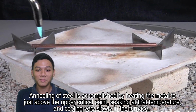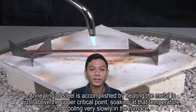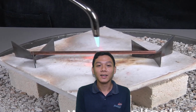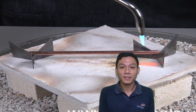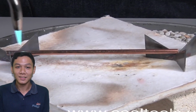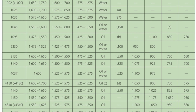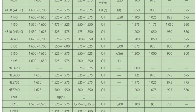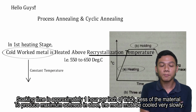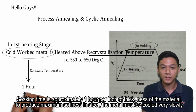Annealing of steel is accomplished by heating the metal to just above the upper critical point, soaking at the temperature and cooling very slowly in the furnace. Now, if you want to know the critical point or the recommended temperatures for the metals, you can pause the video and search for it. Okay, so now the soaking time is approximately 1 hour per inch of thickness of the material.